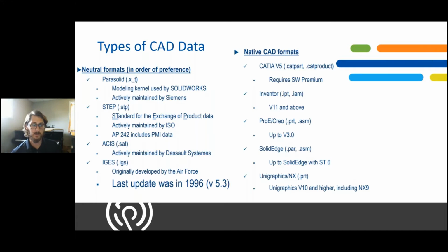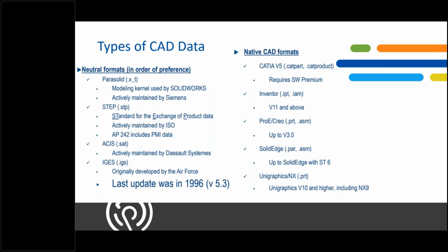And that bold statement at the very bottom is why IGES is the least preferred. It was last updated in 1996. So there has not really been any update to the translation method for that extension for now over 20 years. Not to say that it's a bad option, you just have to recognize the limit that may be introduced as a result. Then over here on the right-hand side, we've got some native CAD files that SolidWorks can pick up and read with relative ease. They're never perfect, but we're going to talk through the process in a little bit as to how we can make them better.